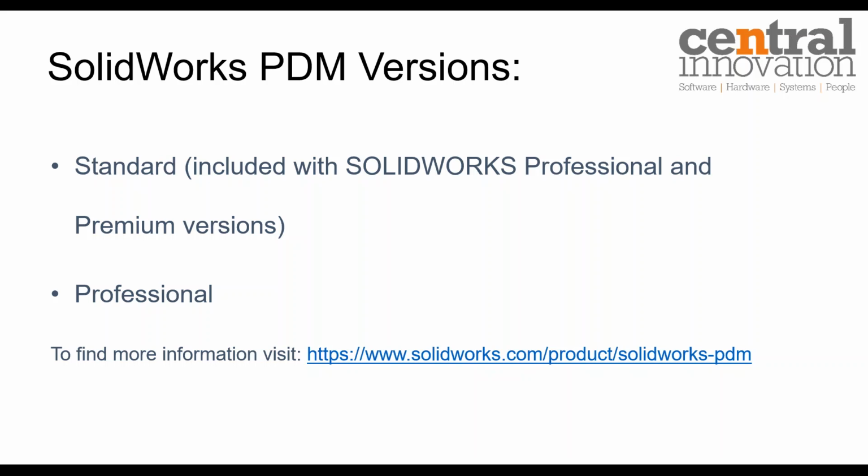The other thing that I like to mention here is that when you want to install SolidWorks PDM Standard, you need to use the Microsoft SQL Express version. And if you want to upgrade to SolidWorks PDM Professional, you definitely need to switch to the Microsoft SQL Standard version. If you want to see more information about the differences between the two, you can simply go to the SolidWorks website and find out more.